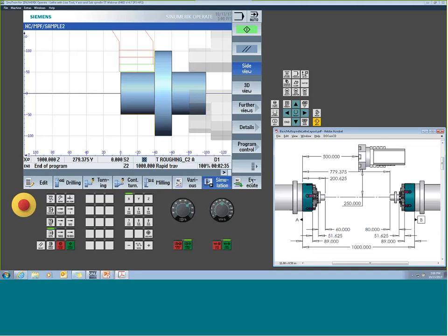So if I was to run it again, since all the offsets are really the same in this case, I'm not going to see any change. What I would need to change, obviously, would be my work coordinate. That's going to be moved out further. So if I do my math, my 89, my 51, I add another 120, that would be my work coordinate of the part. So that's the only thing I would have to reset between these two scenarios.